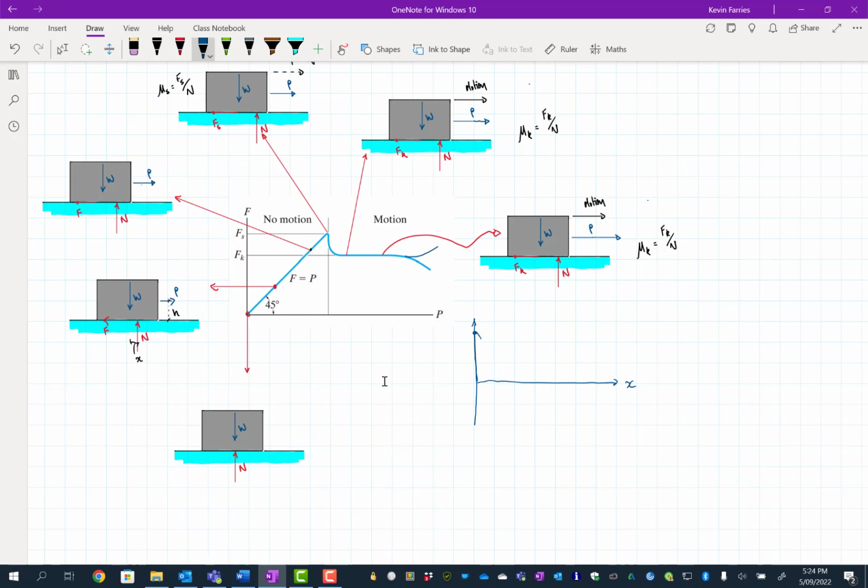And then it might drop away like this, and you might be applying a constant force, and as time goes by, that friction might drop, because it's wearing out the block. Alternatively, it might increase because you're wearing off a low friction coating, or you're losing lubrication as you go along. So probably this end of the graph is better plotted with the distance that's travelled, or the magnitude of the slip, rather than the magnitude of the force.